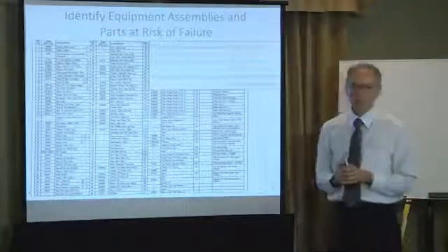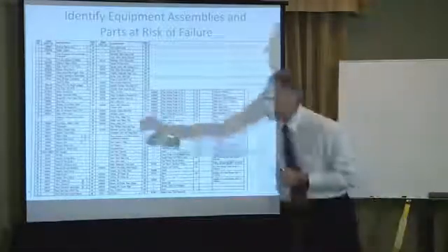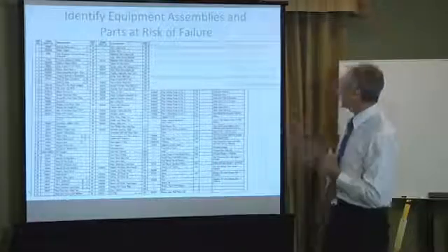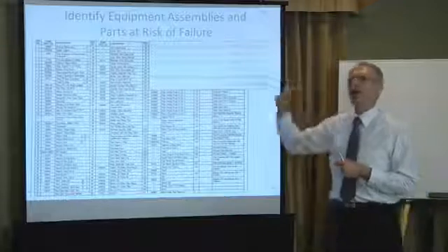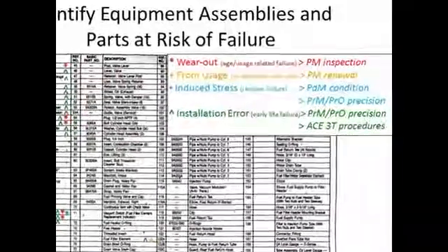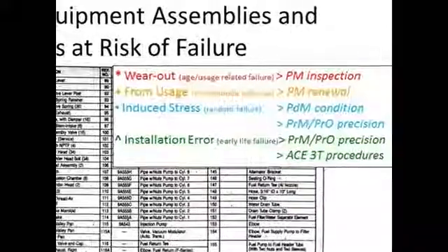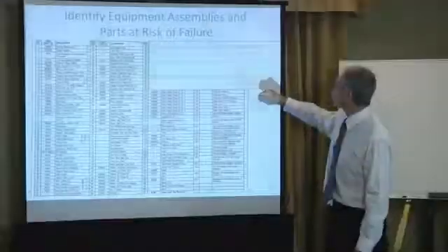Which parts are going to fail from stress? And these are going to be the parts that see high temperature, high loads, high working operating conditions. If I can identify those off the drawing board, then I know I'm going to have to do a couple of things there. One is to monitor their condition, keep an eye on how much stress they're accumulating, and more importantly is to not let them get stressed, because stress is the killer. Some operating practices, I'm going to have precision operation. I'm going to train my guys how to operate that machine perfectly, because I know from the design engineering what its operating zone is. So I'm going to teach my guys, I'm going to design that process of operation, written right down like a movie script, right down to the detail of exactly what to do when and how to do it, and train my guys to this, because I know if I can control stress, I'm going to control reliability.